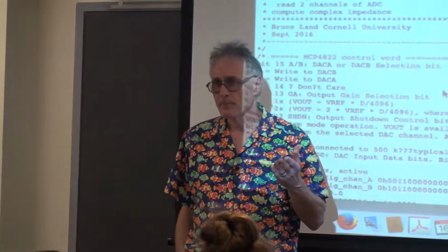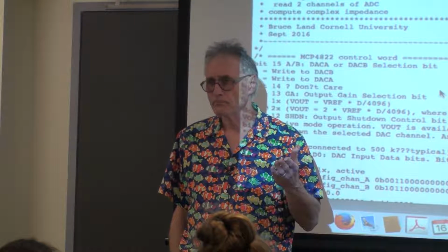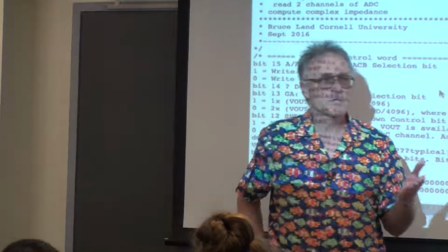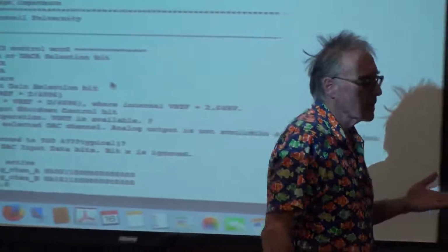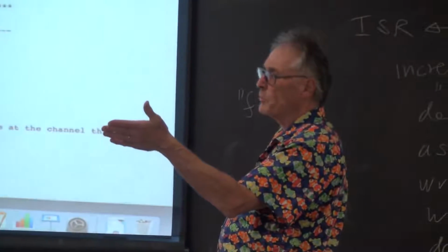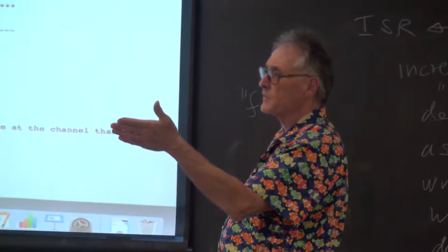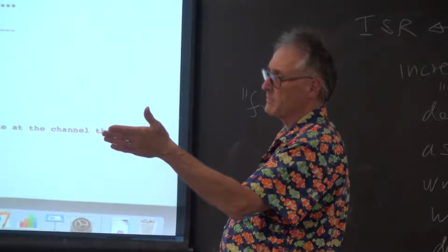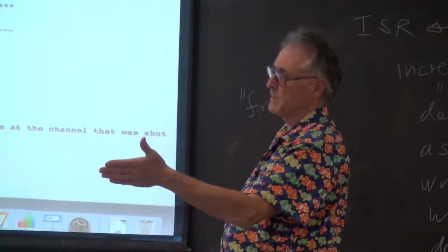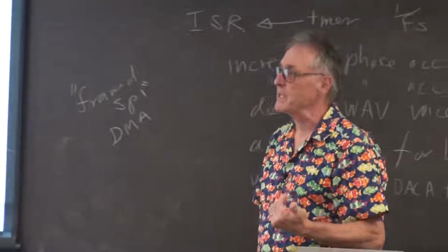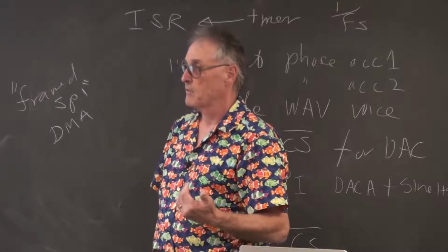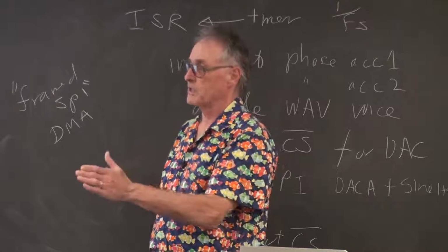Is that right? On this chip? I think that's why it's called an F128. So I think it's 128 kilobytes. So at 100 kilobytes a second, you can store 1.2 seconds of speech if you don't store anything else. That's why you don't want to go fast for speech. You want to go minimum speed for speech to save flash memory, because you're doing a brute copy of a waveform out of memory.